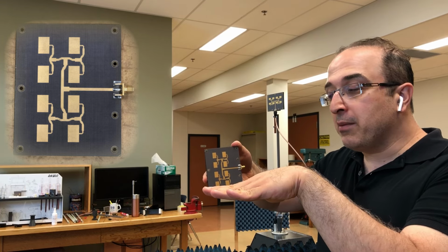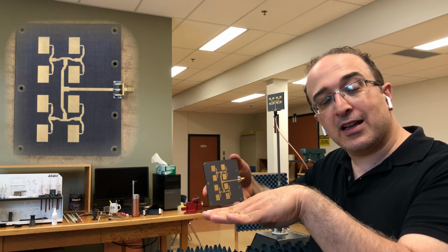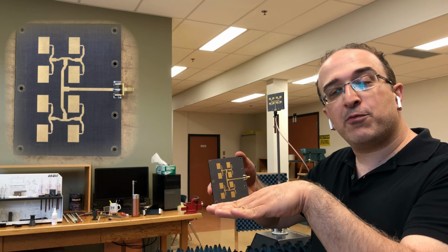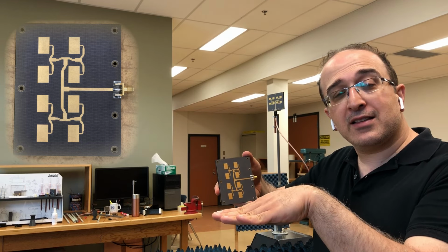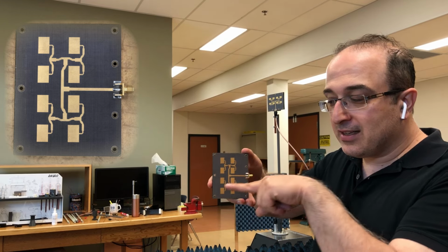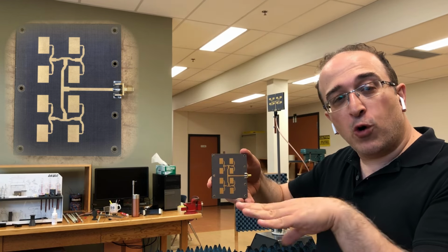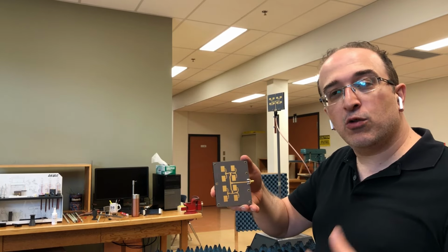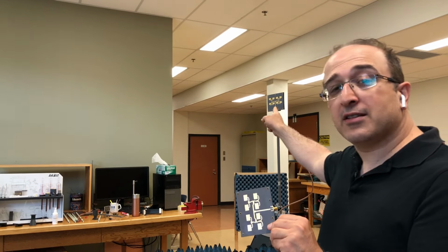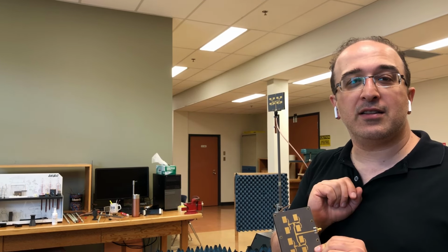Now all of a sudden you're measuring E-plane cut. And remember, because you rotated your antenna under test by 90 degrees, you also need to rotate your horn antenna by 90 degrees to have polarization match. Right now, the horn antenna is providing vertical polarization, but if you rotate your antenna under test by 90, that's the direction of the electric field, so it expects horizontal polarization for copole E-plane. So in this case, you need to rotate the antenna under test by 90 and also your transmit antenna, which is the horn antenna, by 90 degrees, and then you can collect E-plane. So let's go and do that and then start our pattern measurements.